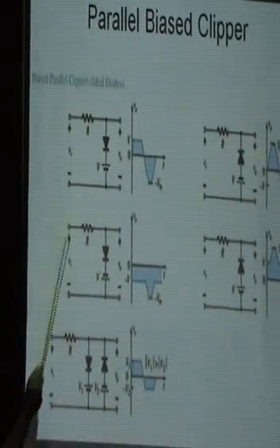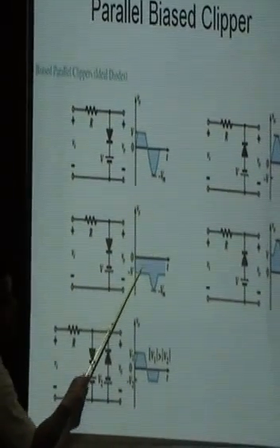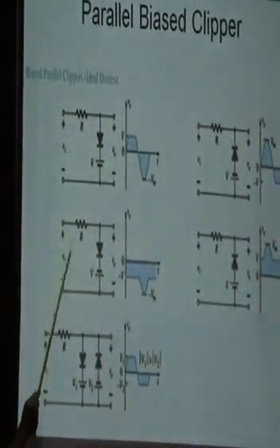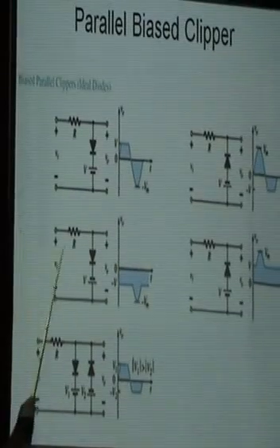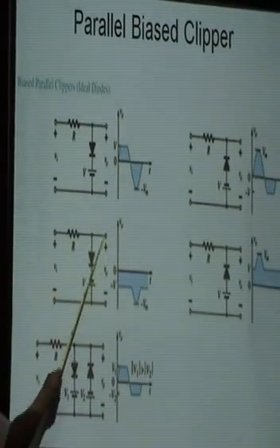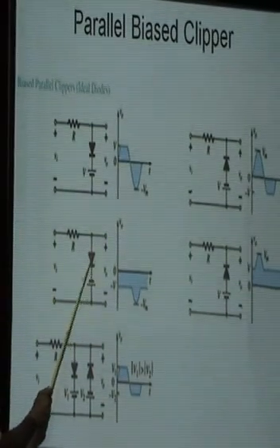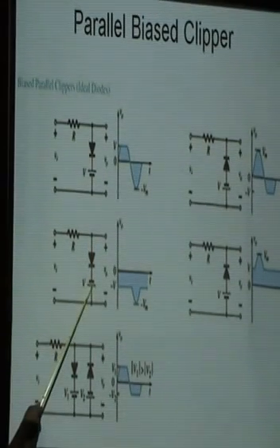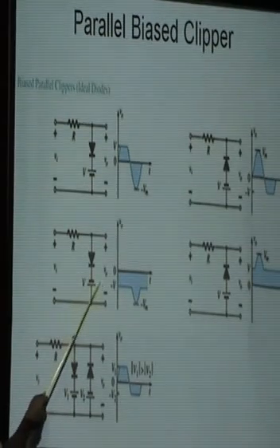But something appears from 0 to pi in the negative phase. Why does this happen? Because for a case, don't consider any input, don't consider any output, replace the diode. Now what is across the output? The battery V, which is always there.